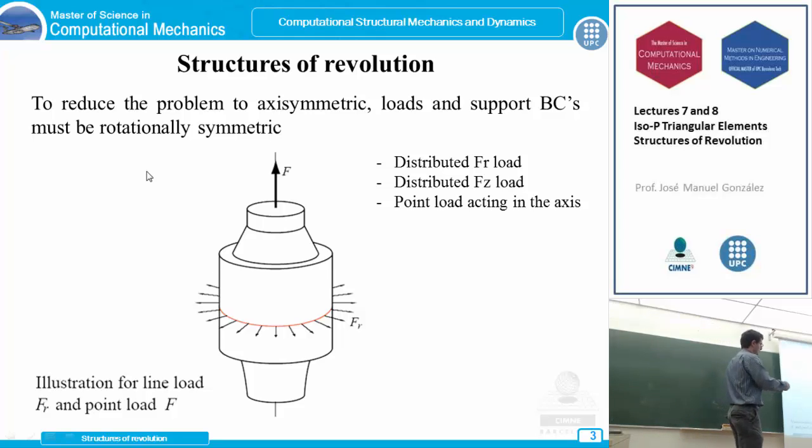And imagine that we have a punctual load which is not placed on the axis. If so, we could employ a mathematical trick, which is to express this non-axisymmetric load using a Fourier development, and then superpose the results obtained for each of these harmonic components.